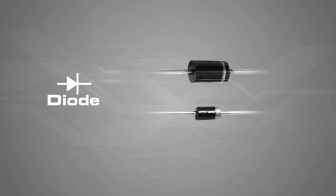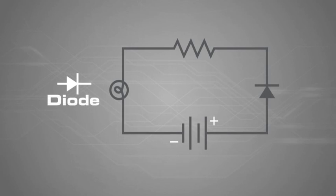It's very important to know which end is the anode or the cathode so you will know if the diode will be forward or reverse biased. A diode that is placed in a circuit with the anode toward the positive terminal of the power supply is known to be forward biased. A forward biased diode will only drop 0.7 volts and the other components will drop the remaining voltage supplied by the power supply.